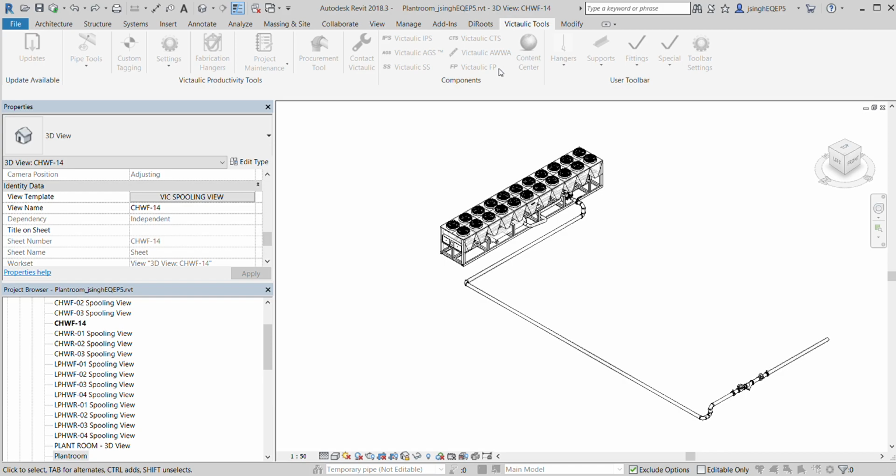Now a very important topic, which is very basic and very important. Why do we create a cut list? Because in Revit I can make a pipe of any size and any segment. Let's say I can make a pipe of 500 meters or 5 meters or 5000 meters. But what happens when you have to procure a pipe from a supplier or manufacturer? All manufacturers make pipes in a particular length. They cannot make more than their standard length.